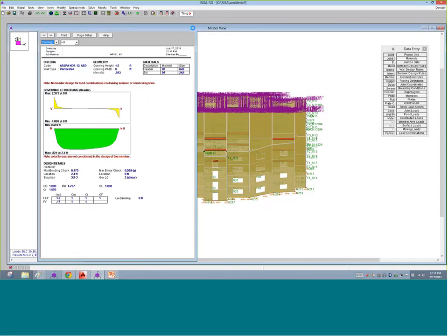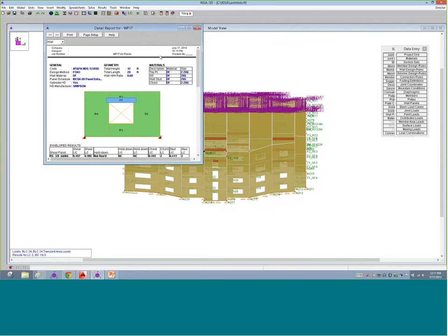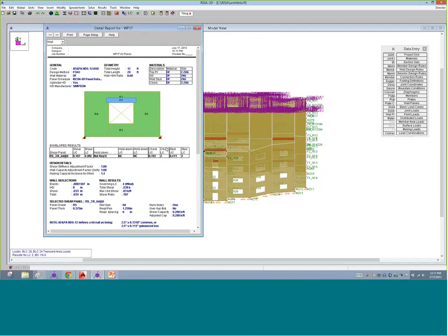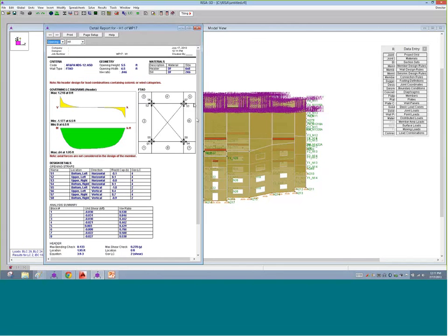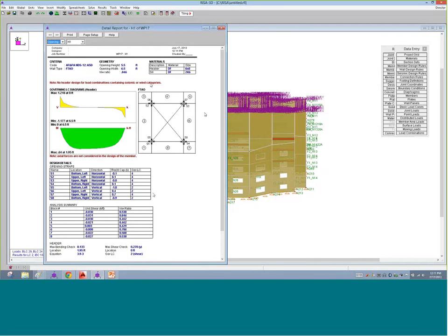Now, force transfer around openings, that last option we mentioned, has very similar reporting to what we saw for perforated. There's no such thing as a region report. We are just looking at the wall as an entire wall. But what is interesting about force transfer around openings is that its opening report is very different. This is where all the work gets done in a force transfer around opening. As I mentioned, those 8 segments or portions are going to be designed individually, broken up into 8 pieces. We have all those numbered around the opening, and we call those block numbers in this report.